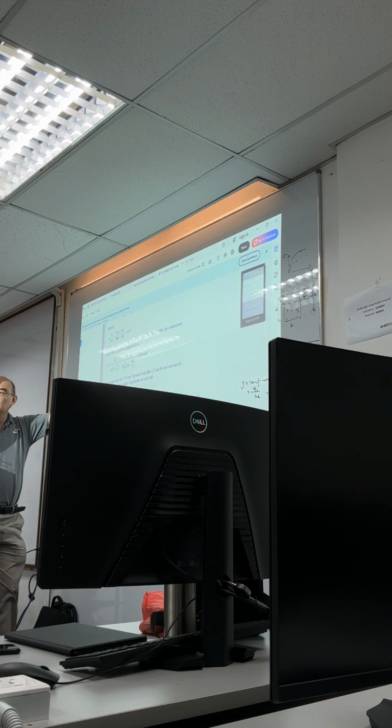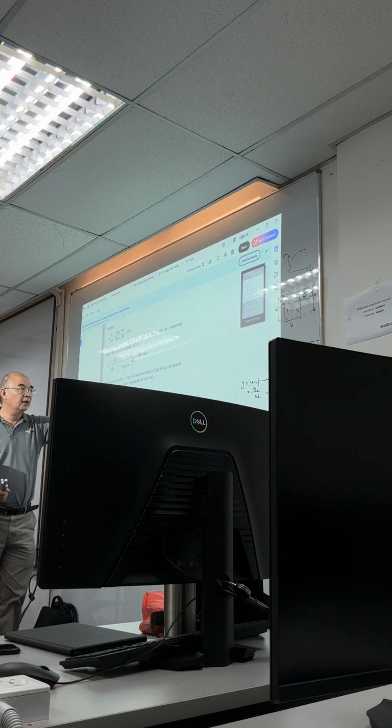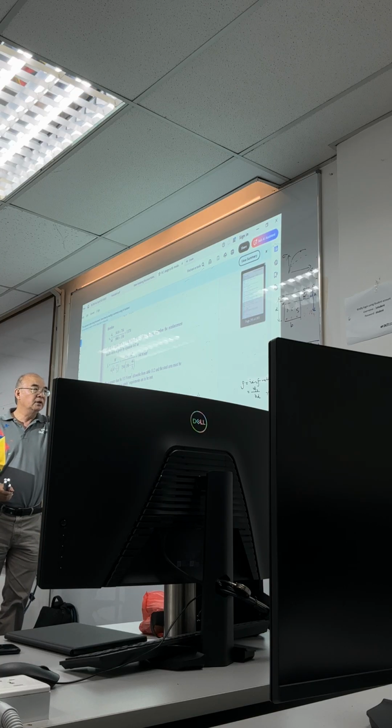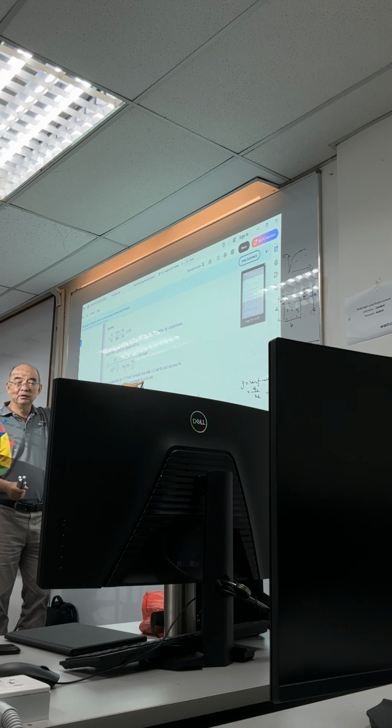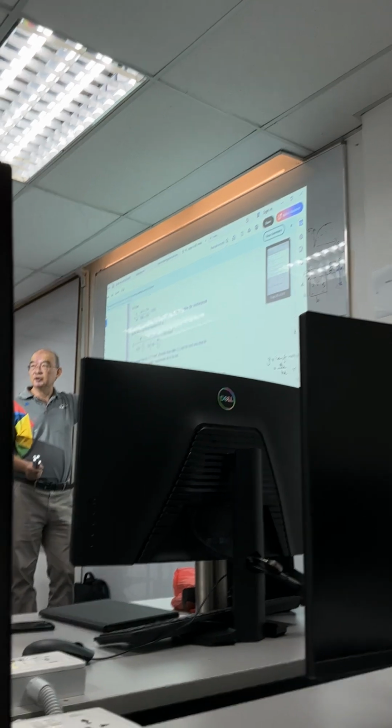He got 144, and the 144 is based on 740. So we increase it to 944. Now he increased to 944, which may be provided as 12 millimeter bars at 110 millimeter center, area 1029. So he further increased this.